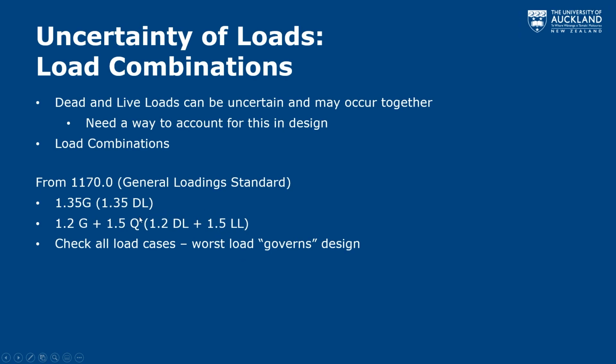So for gravity only, it's typically going to be this 1.2G plus 1.5Q load combination.